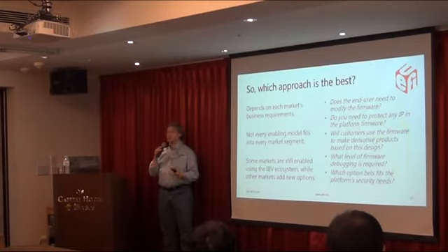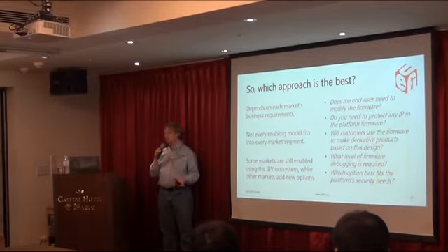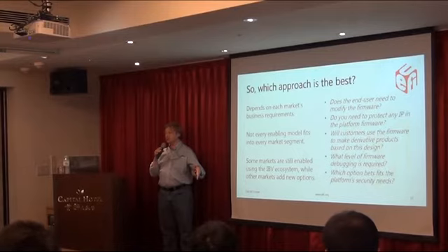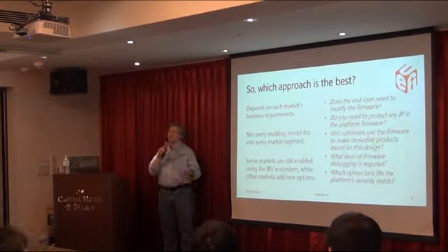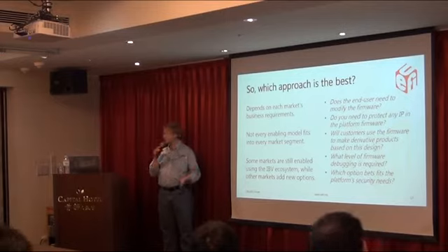Fourth, what level of firmware debugging is required? This is really important. This determines if you go more for an open source level or not, because open source gives you the best firmware debugging capability without involving a lot of lawyers, right? So you've got broader depth of debugging enabled there. But if your target customer isn't going to spend a lot of time debugging the product, that's not really necessary for putting out a lot of source.